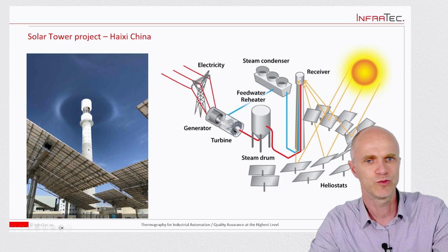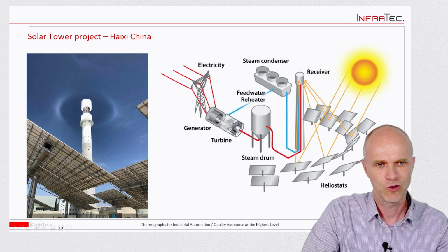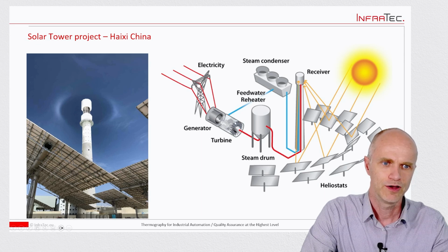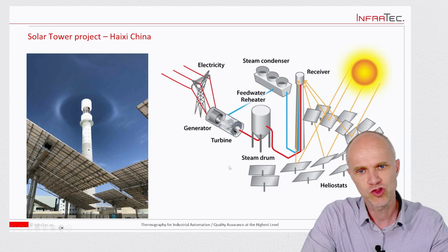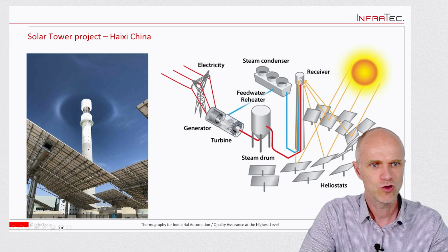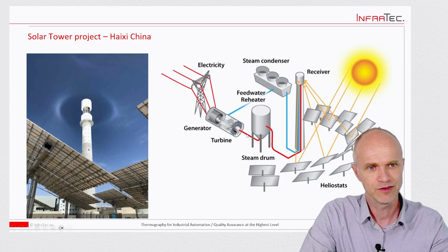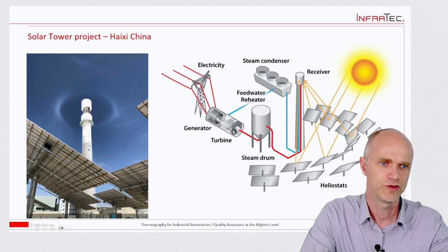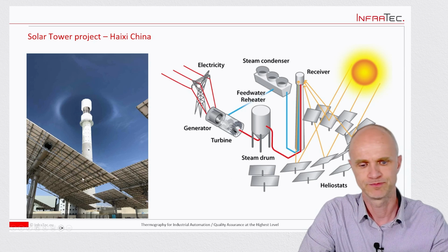And with these 800 degrees, you're heating up a kind of liquid from salt and oil. This makes it possible then to use it with a turbine and then a generator. You can produce electricity. And the good thing is that you cannot just produce energy during the day when the sun is shining. This oil mixture, salt mixture, you can also transfer in the evening into this special reservoir. And then you can also produce energy during the night with the turbine. So all around the clock, you can produce energy with this application.